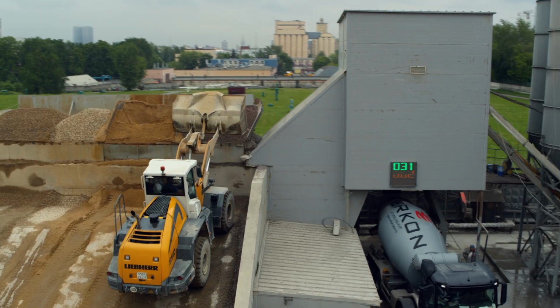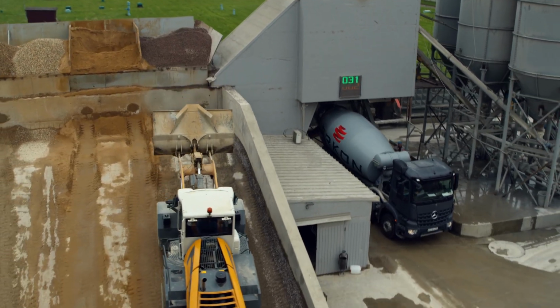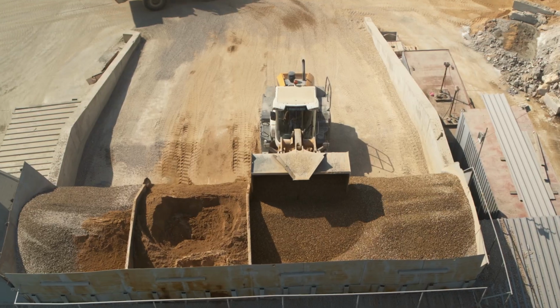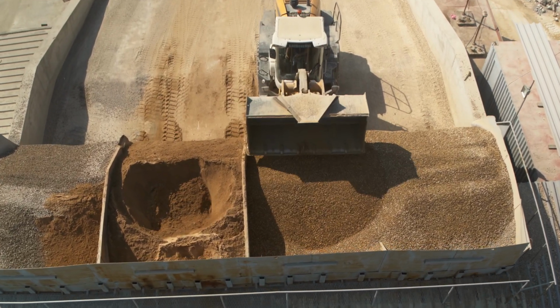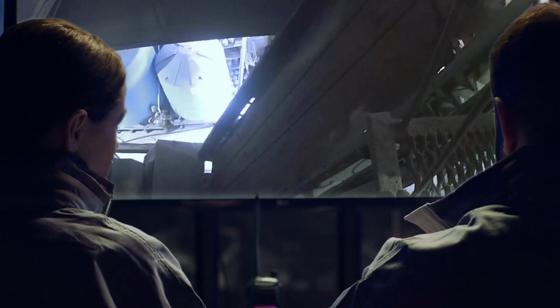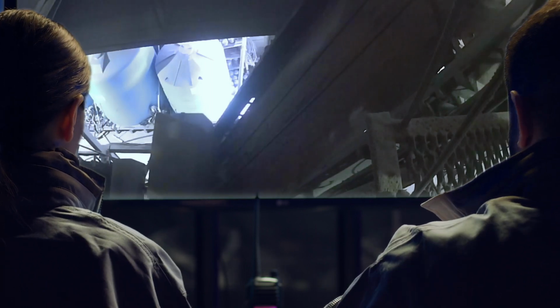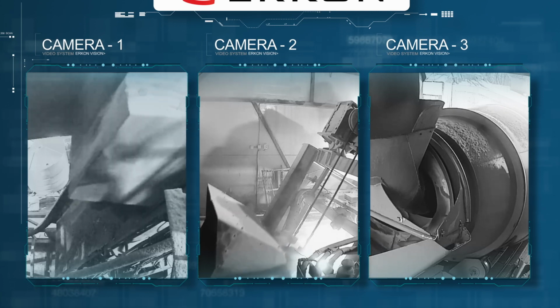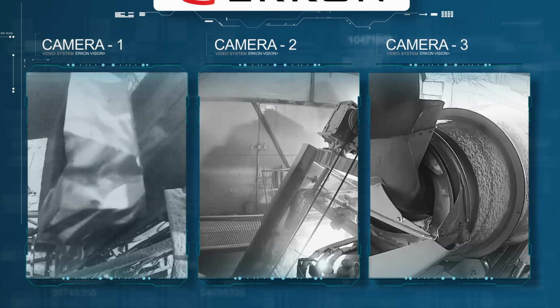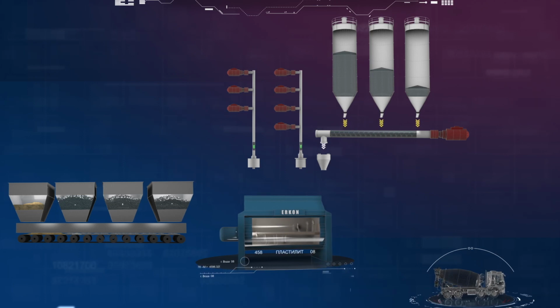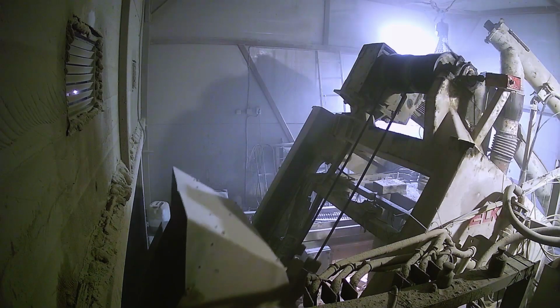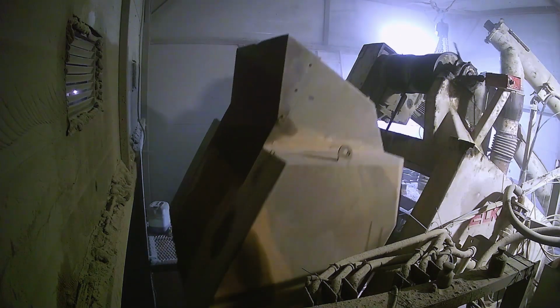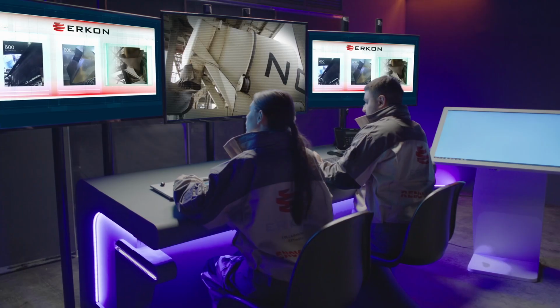And finally, the main and most interesting stage is the production of concrete. Sand and crushed stone from the bins are fed in strictly measured portions to the belt conveyor, and through it they enter the lifting self-dumping basket, the skip. The skip lifts crushed stone and sand, at the same time a screw conveyor with cement starts moving. All these bulk materials are fed into the concrete mixer chamber, after which water is added in the required volume, and as soon as all components enter the concrete mixer, it begins its operation.